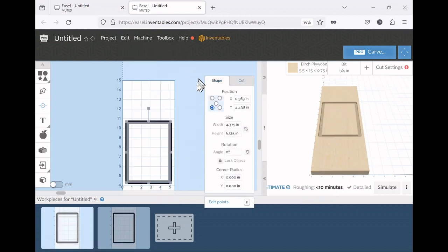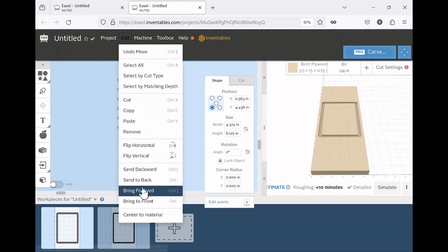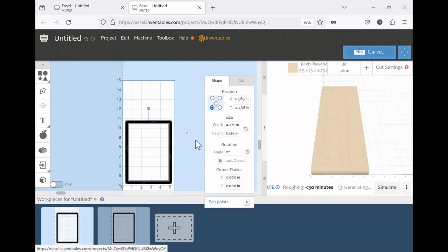We'll notice that rectangle number 2 is sitting on top of rectangle number 1. That poses a little bit of a problem. I think we demoed it in class showing if you take a piece of paper and put it on top of another piece of paper, then you can no longer see the bottom one. Well, the same thing happened here. In order to fix that, we'll have to move rectangle number 2 to the bottom. So we're going to send it to the back. And by doing that, you'll notice now we have our cut over here again.